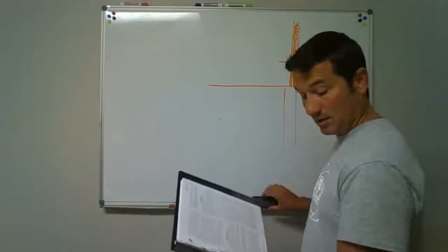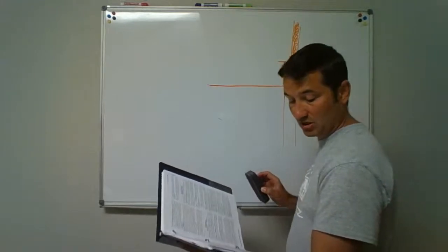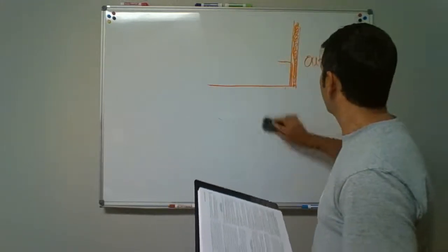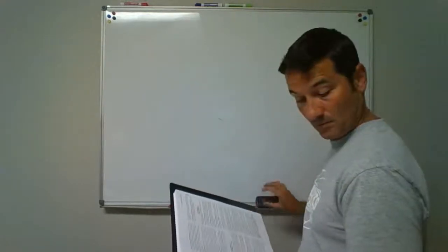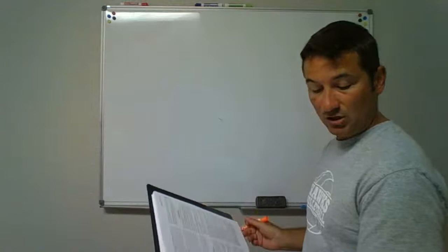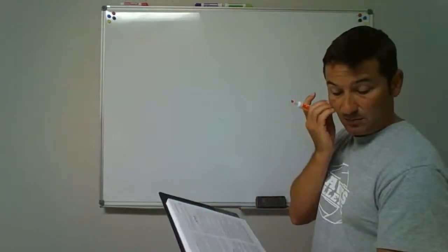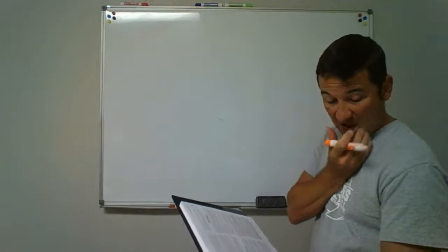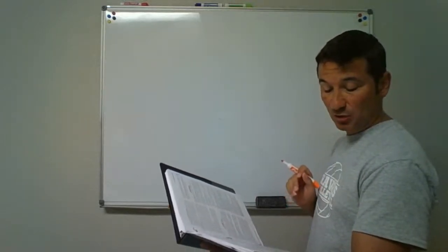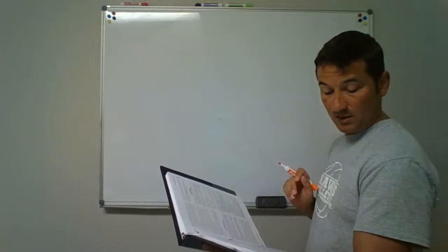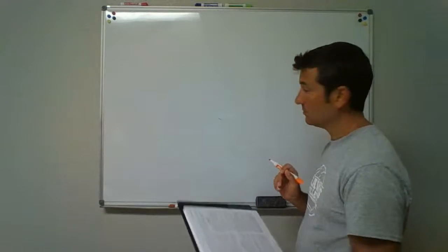The next little phrase there, exterior water supply piping shall be installed, and it's talking about in the ground here. So if I asked you how deep do you need to bury a water line in the ground outside the building? It says installed not less than 6 inches below the frost line and not less than 12 inches below grade.